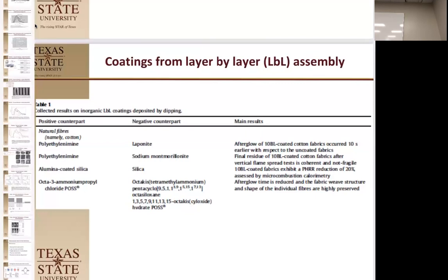It's a thorium oxide, no, zirconium oxide that forms the mesh after you sinter it. It's really fragile after, but it's flexible. So there's that, having a coherent and non-fragile system. With just silica and aluminum-coated silica, there's no organic binder at all. You're looking at completely inorganic binders.